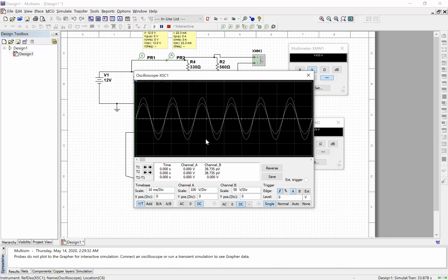And we could actually measure the frequency from this by counting how many divisions, or fractions of divisions, make up one waveform. To measure that, the easiest way is actually to measure peak to peak, as opposed to trying to read the middle. Although I know this scope's middle is truly the middle, and that's easy, peak to peak is sometimes a bit easier to see.